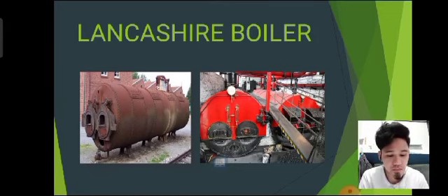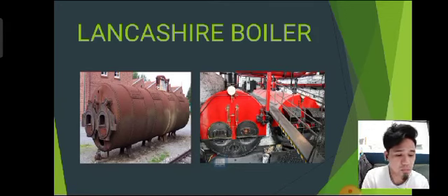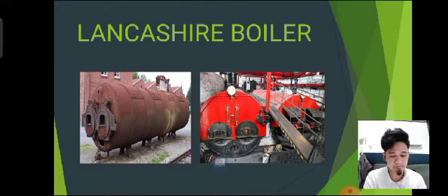Lancashire boiler. This is a photograph of a used Lancashire boiler. Here you can see the grate where the fuel is burnt. The flue gases flow along the axis of this tube and then emerge, because this vessel is placed in brick masonry.